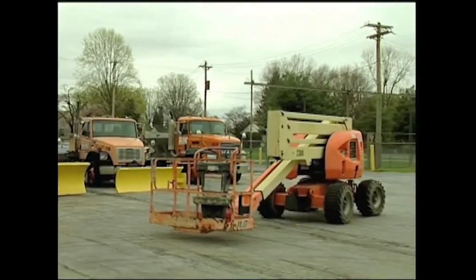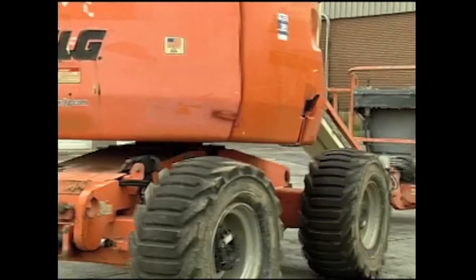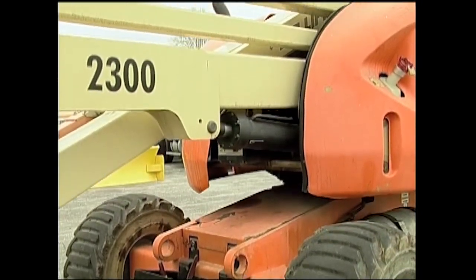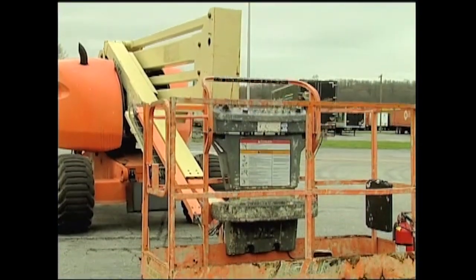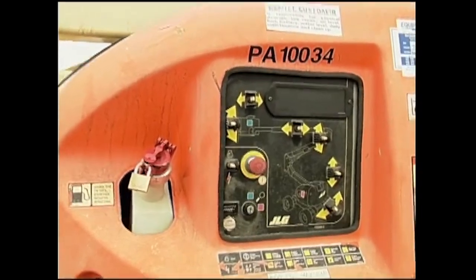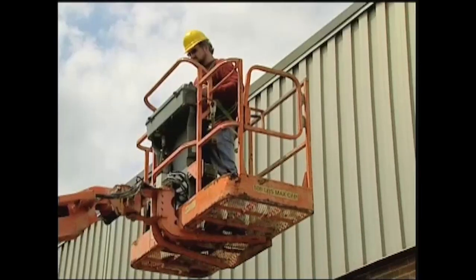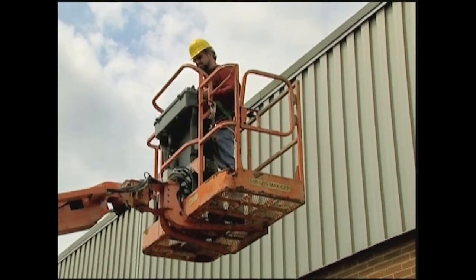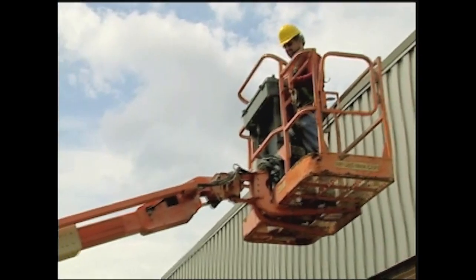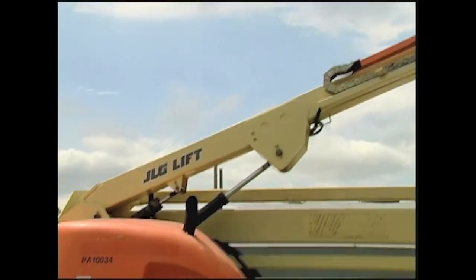Most aerial lifts are made up of four major elements: a base with supports for the lift's platform or bucket, a lifting mechanism, the platform or bucket itself, and controls, which are often located on both the base and the platform. The main difference between the various types of aerial lifts is in the mechanism that lifts the platform. Typically, it's hydraulic, pneumatic, or driven by electrically powered gears.